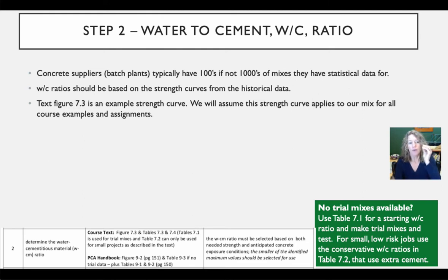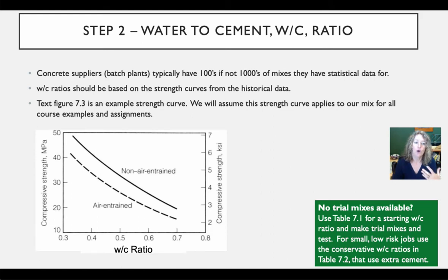Now, what a strength curve looks like is something that says, okay, for a set water to cement ratio, what sort of strength, either in KSI or megapascals, can I expect?